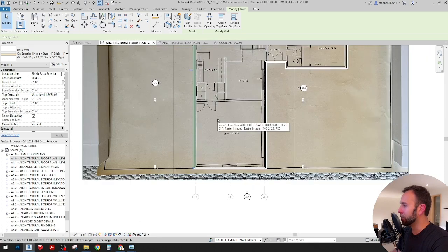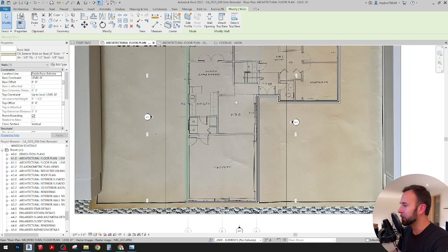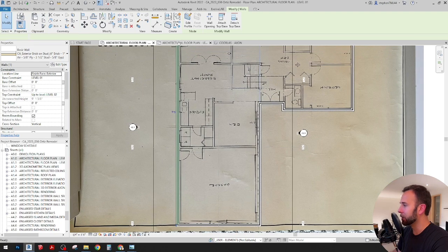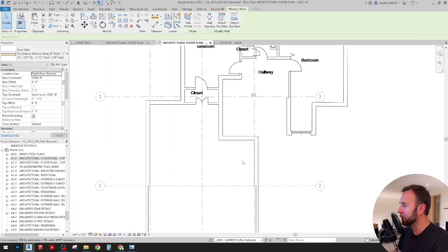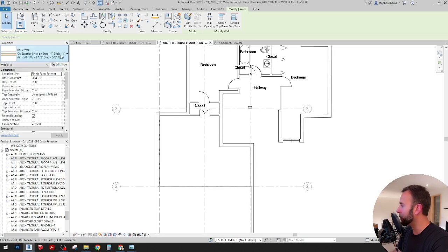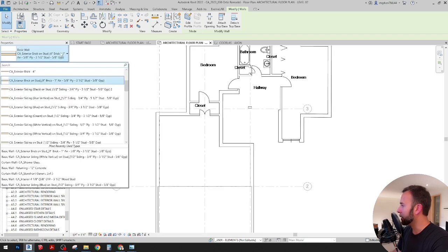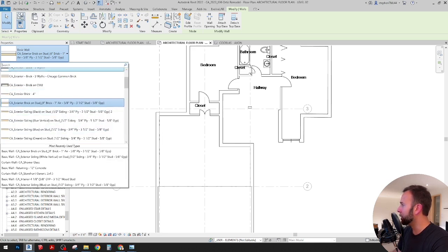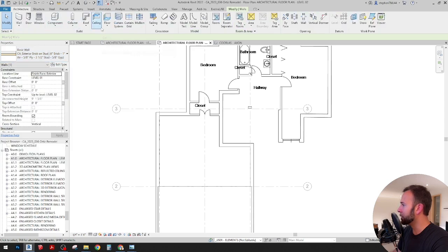Now that we got our floor in that area, we'll do the same thing for this area, and maybe up above we can see exactly where that would go. I'm assuming, since it's an older building and we have some smaller spans, that the joist depth is 2x10.